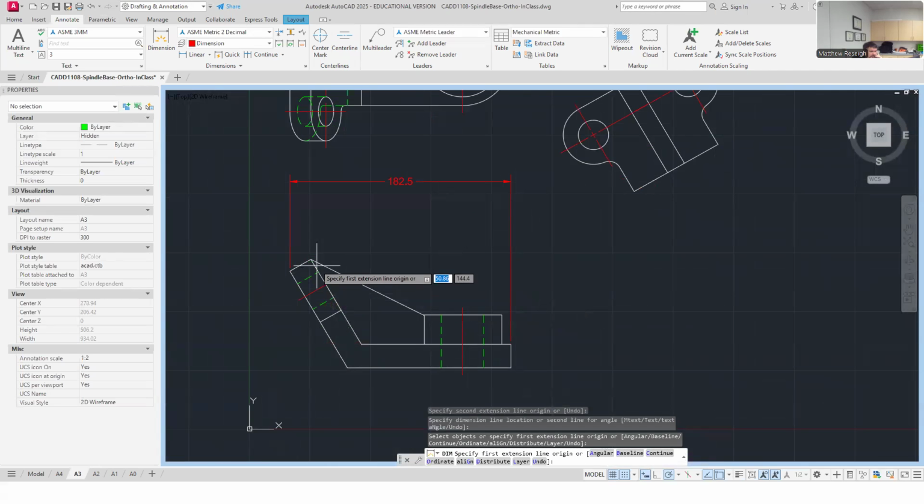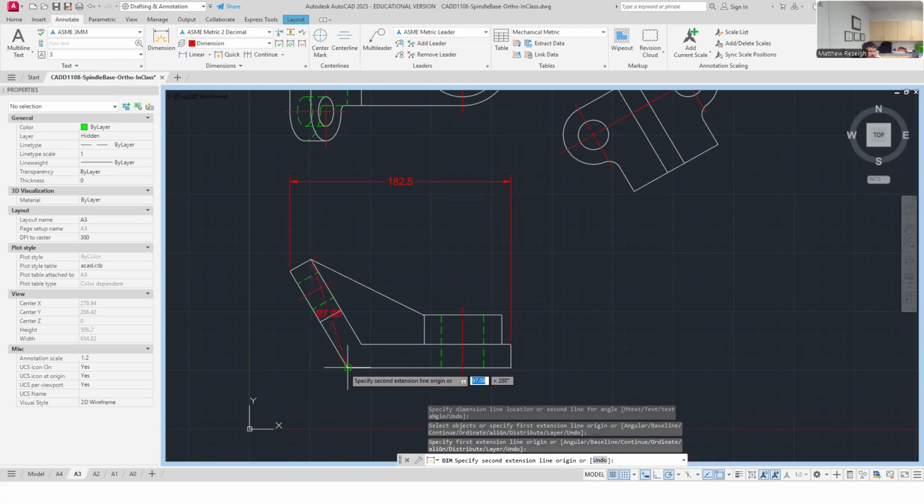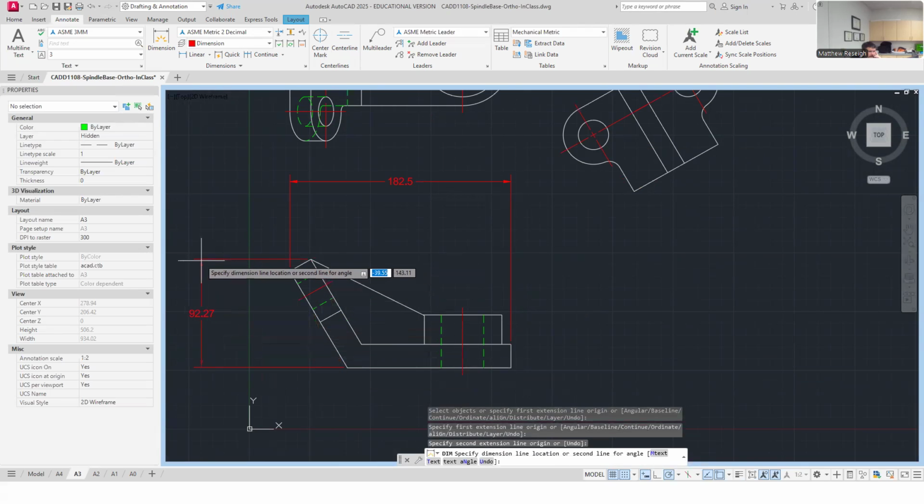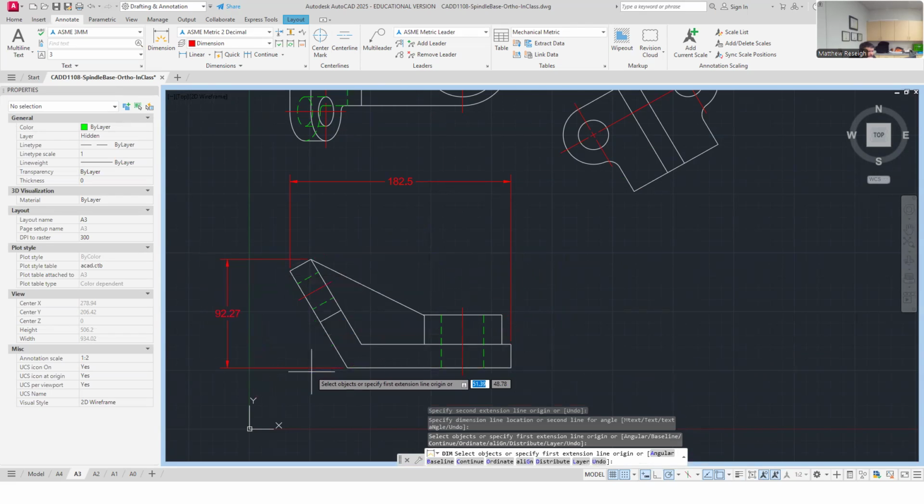So I can put that either side, really. I'll pull it out here to the left right now. I know that that necessarily isn't in between views, but it's kind of closer here rather than pulling it maybe clear across. This isn't wrong either, though. I could go either way. If I do this, remember, I got to tuck my extension lines back to the object edge. I call out a lot of people for remembering when you do stuff like this to tuck your extension lines back to the object edge, even if it's just a small object that you're overlapping. But yeah, so I'll just drop this here mostly for clarity's sake and less extension line.